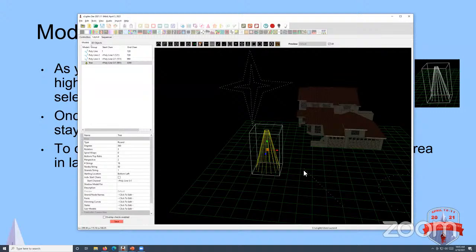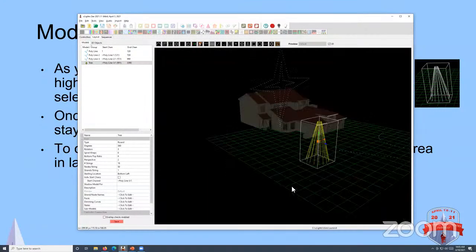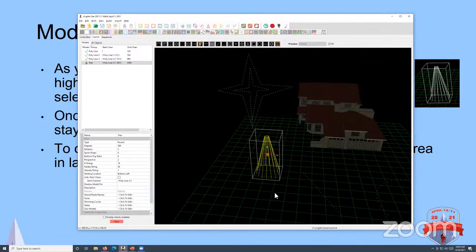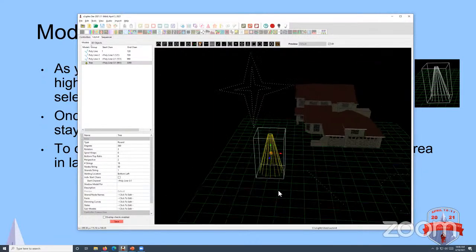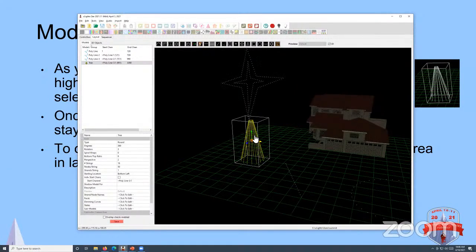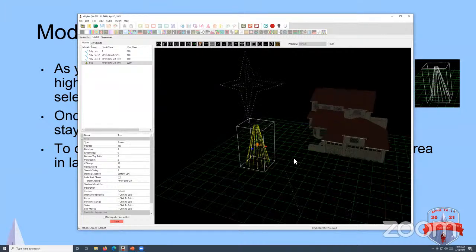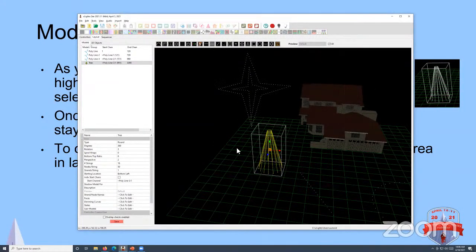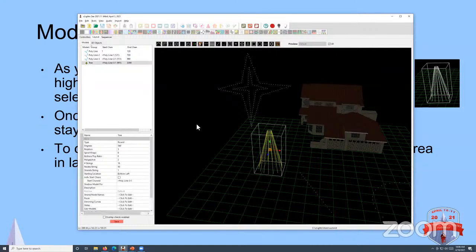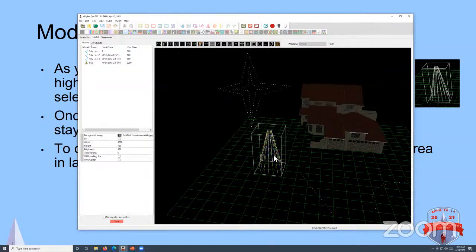Then that allows me to just pan around while it's still selected. So that's the reason why you're able to let go of the mouse and then move around, so you can zoom in on your handles and do what you need to do. But to release that, you can double click out somewhere where there's nothing else, or you can hit the escape key that will deselect.